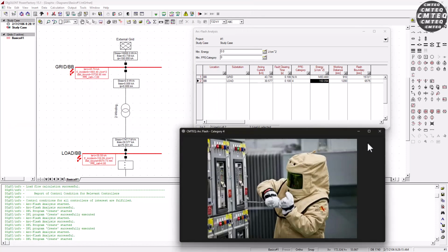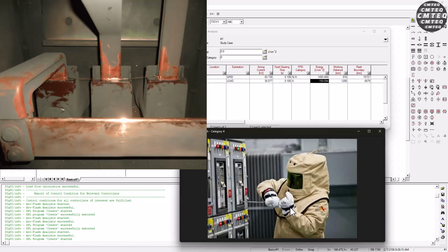Great stuff. So this is why arc flash studies are not just compliance exercises, okay? They are critical in terms of design optimization and safety planning in electrical installations and substation setups, okay? So by analyzing these types of results, we can obviously define the PPE level as we've seen, adjust protection settings to limit exposure to incident energy, and also implement arc resistant design for substation safety.